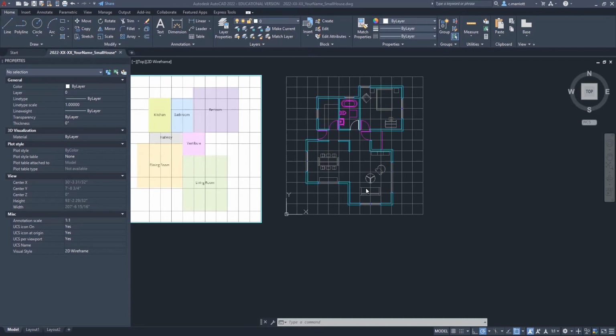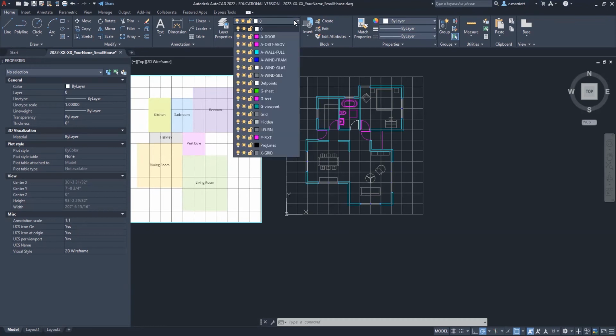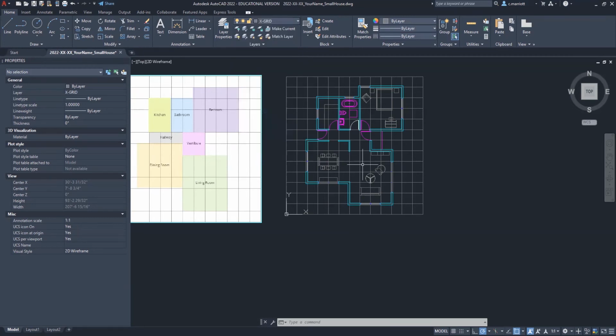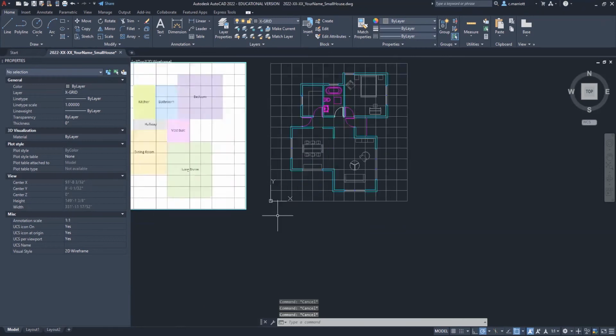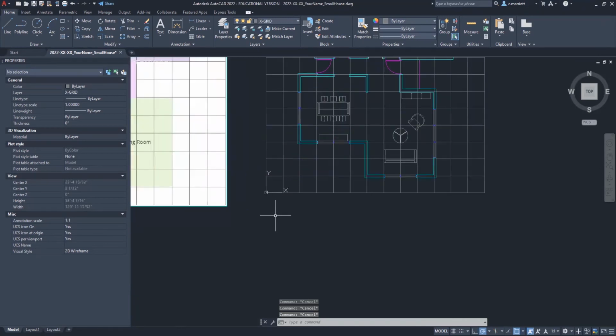And I'll use the projection method, which basically permits me to track lines down, so I don't have to keep remeasuring and redrawing in that way. I can use some information that's already there. So the first thing I'm going to do is set the current layer to the grid layer. I think you may have one called X grid, whatever you use to draw the grid that you've already got in place. And then I'm going to start drawing some guidelines down below the floor plan.